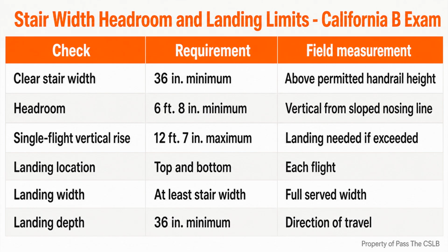I do not compare a rough stair to a finished stair and assume the numbers will remain the same. I coordinate the thickness of the stair treads, the finished floor at the lower landing, and the finished surface at the upper landing. Each layer changes where the foot actually starts and where it lands.